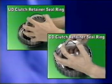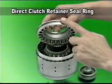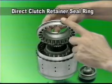Two seal rings should be checked too, which are installed at the return spring retainer, namely the centrifugal oil pressure balancer. In the 5-speed automatic transaxle, the centrifugal oil pressure balancer is installed at the direct clutch. Check the seal ring damage of it too.